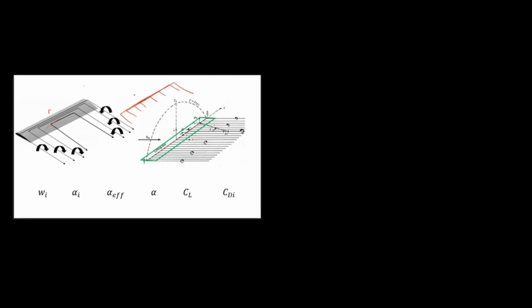Like this, he superimposed all those lines into a single line. So then he found the downwash induced by these semi-infinite vortices, then alpha L, CL, CD, etc. And here you see these trailing vortices produce downwash everywhere. But we are interested in finding the downwash velocity acting on this wing. We are not interested in finding the rearward position, etc. So this is the trailing edge vortices.